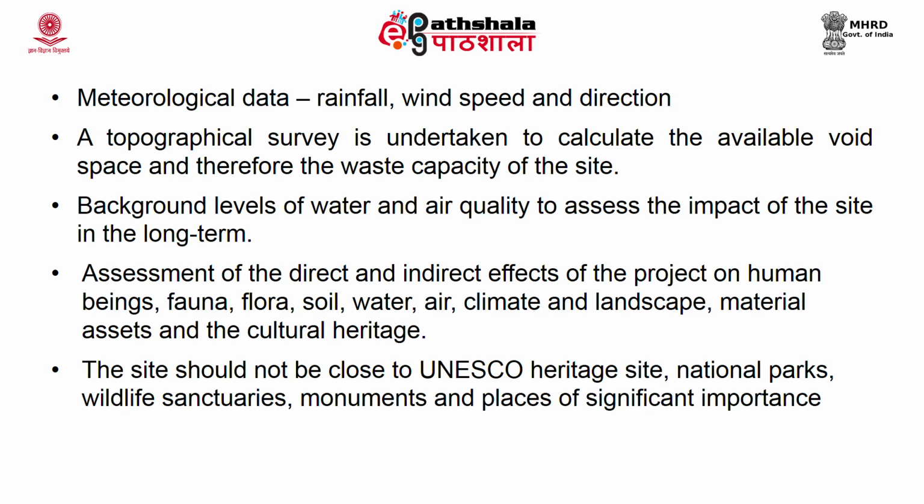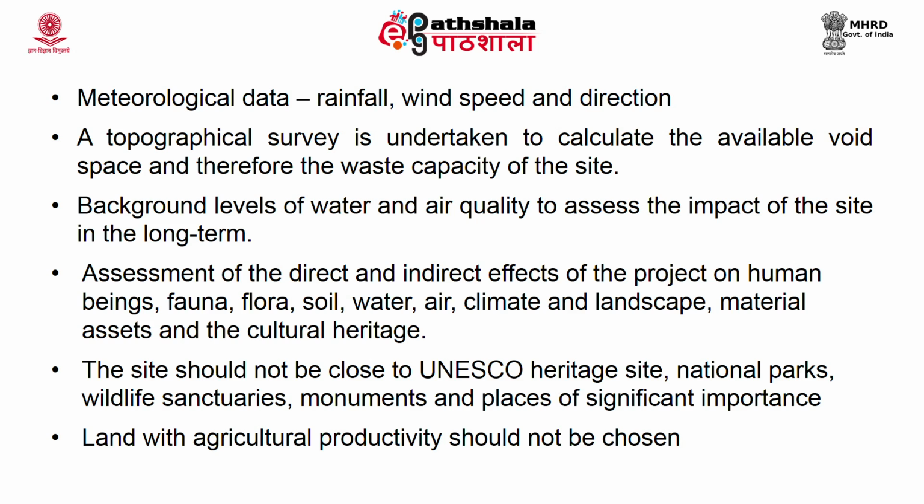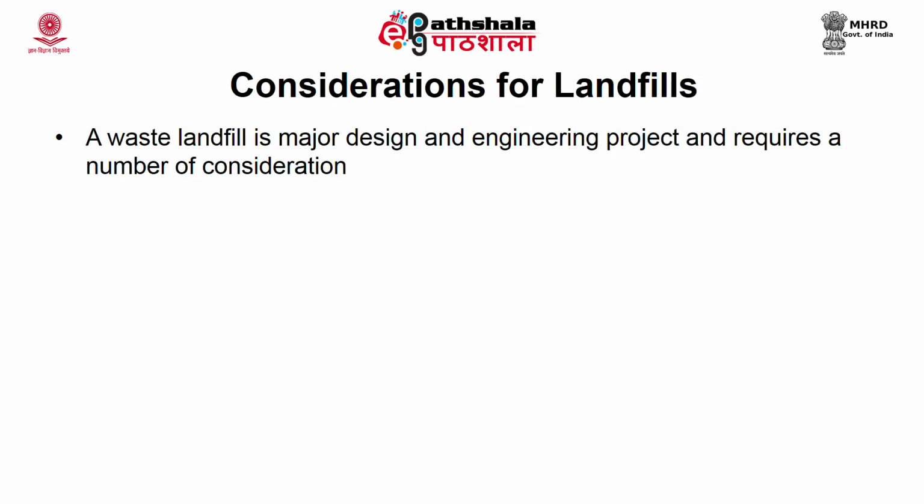Apart from this, you also should take care that these landfill sites are not located near a UNESCO heritage site, or near a monument, or near national parks and wildlife sanctuaries. You should also not select land with good agricultural productivity. Even land which is barren and which can be brought back to productivity should also be avoided when you select the site for landfilling. Now let us look into the considerations for landfill.